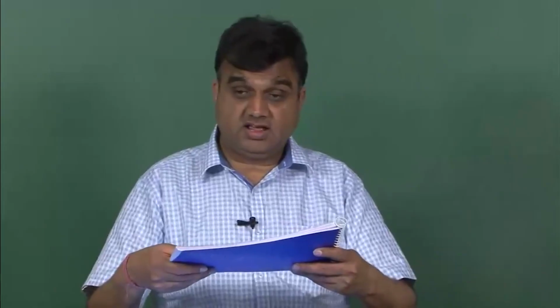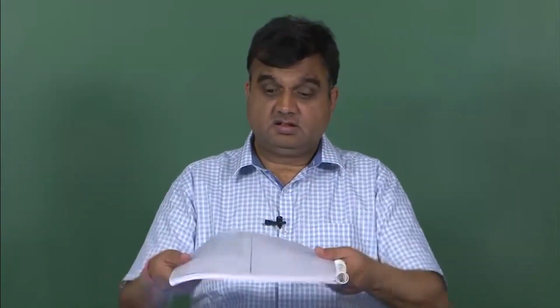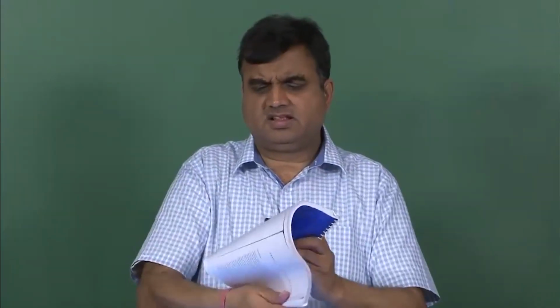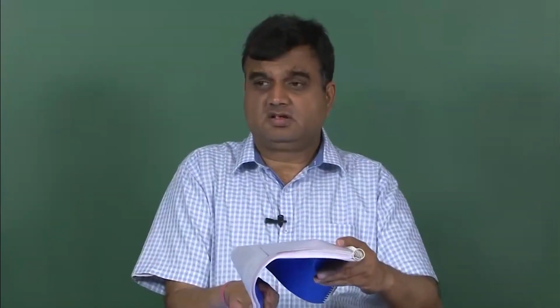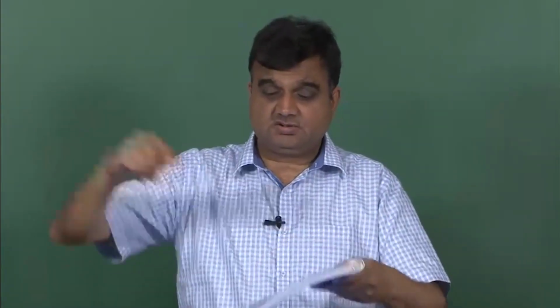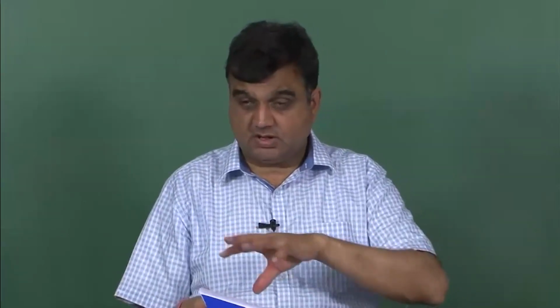And then there is something called Kxy. And what is that? So, this is bending, this is also bending, but then I can also twist it like this. In this case, it is having curvature in this direction also, it is having curvature in that direction also, and it is also a cross component.